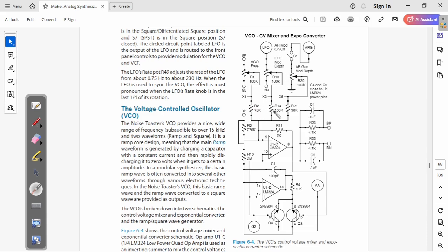That's why you have different resistors here, R2, R14, R21, depending on the input. So it's just a very simple amplifier attenuator, because it's probably attenuating the signal. You have 2K over 75 or 100 or 36K, so it's not even an amplifier.